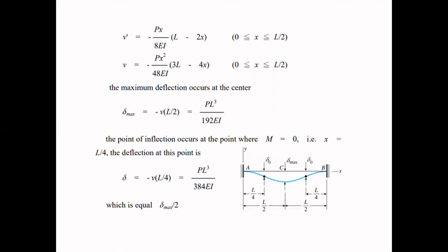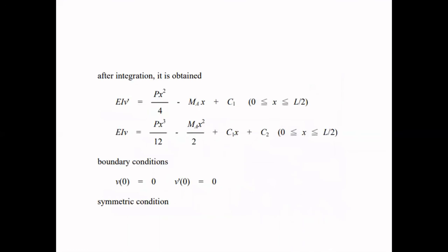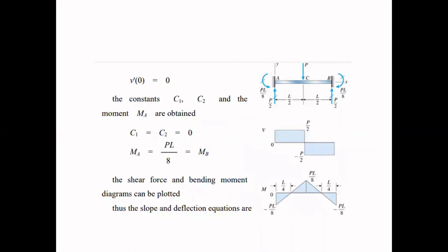fixed beam also. Remember one thing we need to see in this case, as well as in the case of propped cantilever beams: when we calculate the shear forces and the bending moments, we need to calculate the reactions first, because then all the reactions are known to us. Similarly, in this case, this is basically an indeterminate beam. So in this indeterminate beam, there are three support reactions over here.